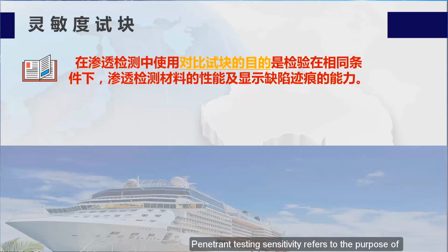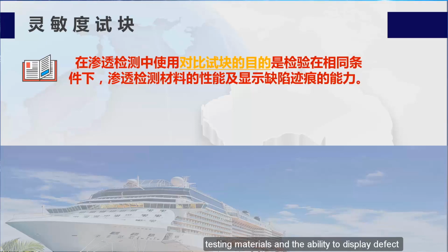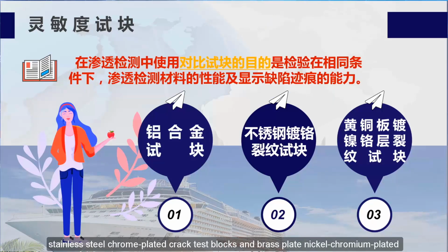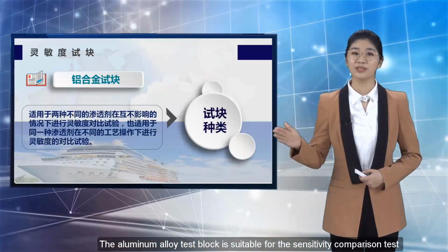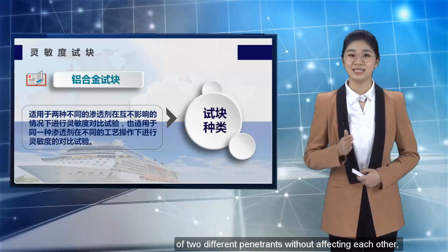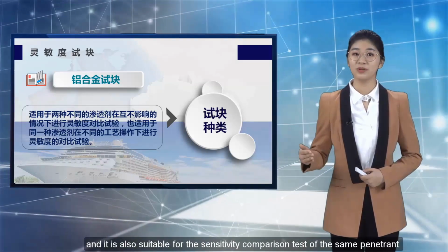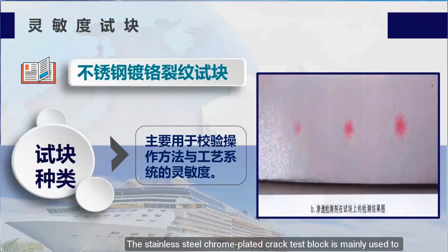Penetrant testing sensitivity refers to the purpose of using a comparison test block in penetrant testing to test the performance of penetrant testing materials and the ability to display defect traces under the same conditions. Commonly used test blocks include aluminum alloy test blocks, stainless steel chrome-plated crack test blocks and brass plate nickel chromium plated crack test blocks. The aluminum alloy test block is suitable for the sensitivity comparison test of two different penetrants without affecting each other. And it is also suitable for the sensitivity comparison test of the same penetrant under different process operations. The stainless steel chrome-plated crack test block is mainly used to verify the sensitivity of the operation method and process system.